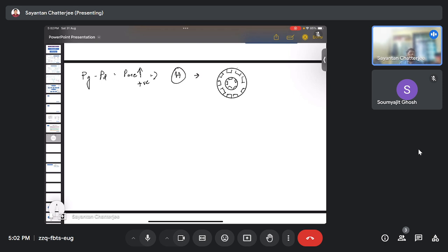Let's consider the case of a four pole machine, with north pole and south pole. In the rotor we pass DC, and this DC current leads to a flux. When this flux cuts the stator side, it produces an EMF, and based on that EMF the current starts flowing. But this EMF tries to oppose the cause that produced it. That is Lenz's law. Firstly it's Faraday's law, and then the negative sign is due to Lenz's law. So Faraday's law and Lenz's law.